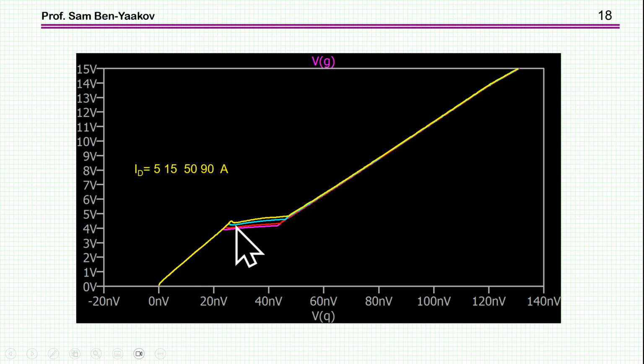Now, the higher the current, the higher the voltage you need at the input, because of course the gate voltage is affecting the current through the transconductance. So the higher the current, the higher the voltage momentarily you need at this point in order to reach the current of, in our case, the current source, and in reality, the inductor current. So we can get this information very nicely.